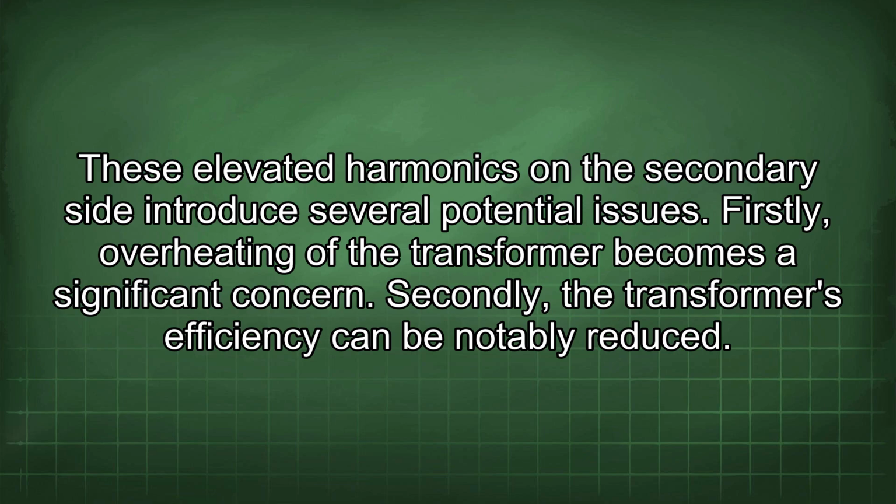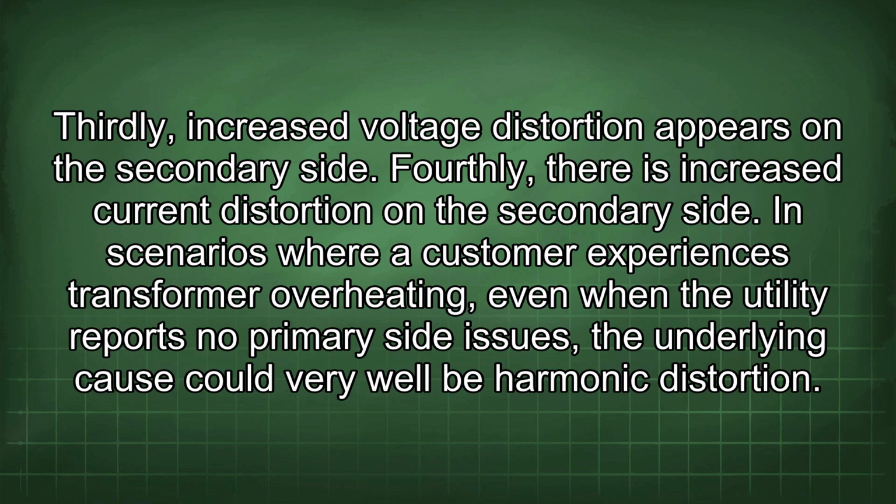Firstly, overheating of the transformer becomes a significant concern. Secondly, the transformer's efficiency can be notably reduced. Thirdly, increased voltage distortion appears on the secondary side. Fourthly, there is increased current distortion on the secondary side.